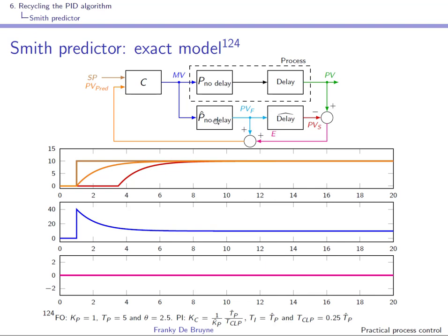The PI controller is tuned based on the knowledge of the model, and since here we want to accelerate the system, this will yield a controller gain of 4, and this is why when the set point change is done, this error at the time of the change is producing a proportional kick of 40.